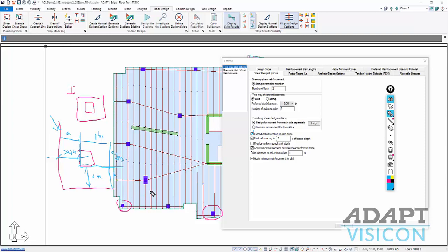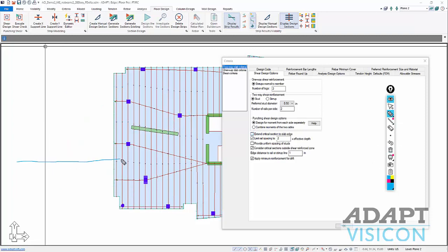The same condition could occur for, this is a corner condition. This might be, for example, an interior condition, four-sided, and this is an end edge condition here. I'll call it E/E. This condition is treated similar to the corner, where we have a free edge. We might have a slab or a column here, and the program looks in this direction. This is less than 4 times h. This direction is not, nor is this direction.